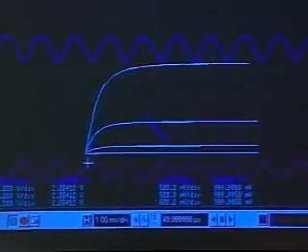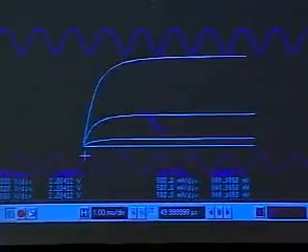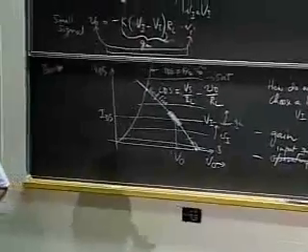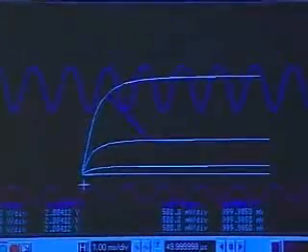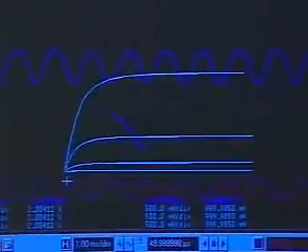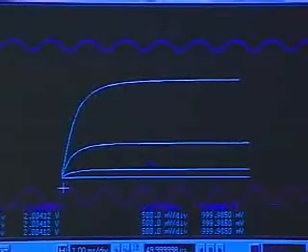Pardon? It increases, exactly. So if I increase the bias point to here, then this must also increase because my gain has increased. Okay, let me do that. So let me increase the input bias. You indeed notice that the region of the load line articulated is larger now. Let me decrease the bias, and notice that because the gain is smaller, the little segment shown is also smaller.